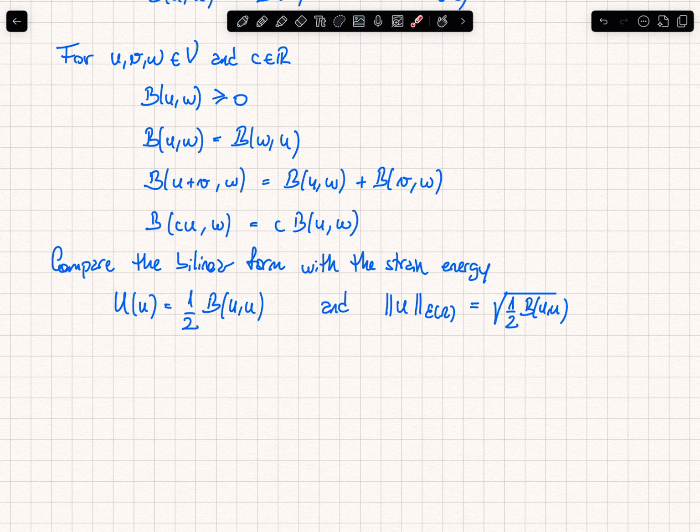And this is very interesting, right? It's very interesting because now I know that the bilinear form is going to lead to a structure of my discrete system where the stiffness matrix is going to be that left-hand side of the equation, right? And now I can measure things using that. I can use the bilinear form and the resulting stiffness matrix to measure things in these functional spaces.